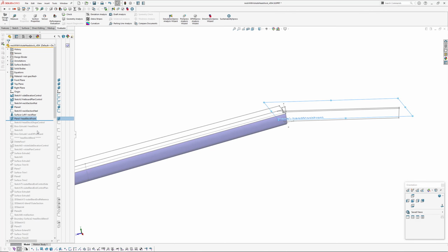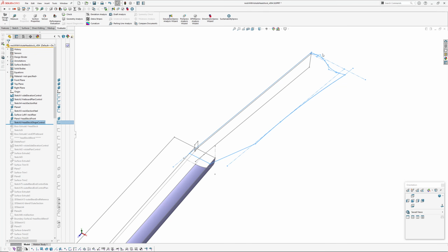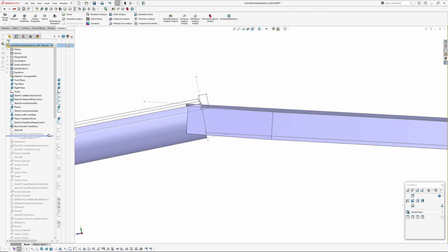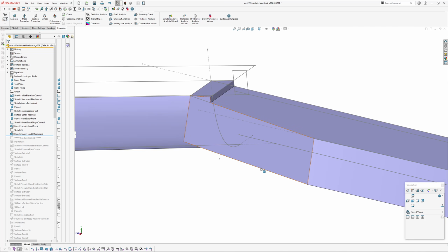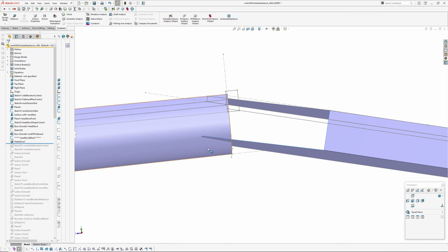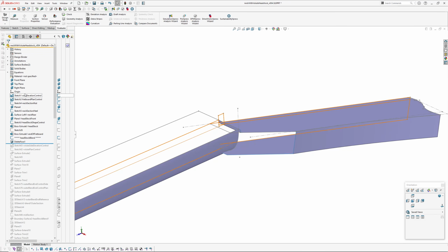Headstock front is just a plane through that control sketch, and then my headstock control sketch there for the profile on the outside of the headstock. And I've got a boss extrude for the headstock, and then the end of the fretboard, just like a little nublet there, which is merged into the solid. And then the first thing I do when I get into the headstock modeling is I just delete this side face here to turn that solid into a surface model.